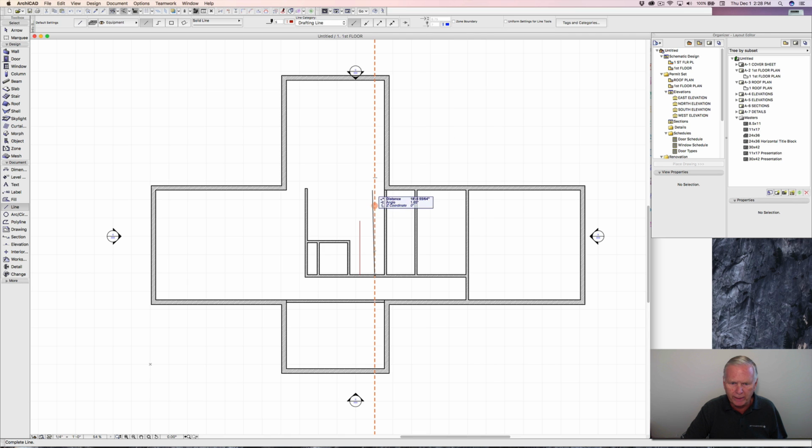But if I want to bring it up and align it with that point right there, what I have to do is hit the Shift key, and that will hold the line on that guideline, or hold it on any guideline that we would come to. And it'll hold it there, and then we can move our mouse over to that point. When that little pencil turns black like that, we know we're right at that point. We can click, and we've stopped that line right in line with that point. We'll click, close that up, and that's the end of that cabinet.